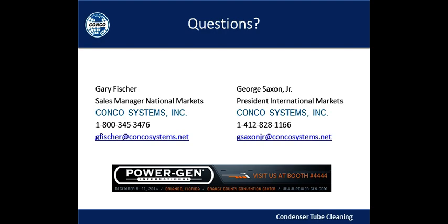Sure. That's a different type of system. That is actually what we call our Excalibur. It is a brush at the end of a shaft, and the shaft is connected to a motor, which actually rotates that brush. Typically, that type of cleaning system is used on specific applications, such as U-tube heat exchangers or heat exchangers where you cannot take off the back end so that you can't collect the cleaners themselves. You would be able to use this rotating brush.